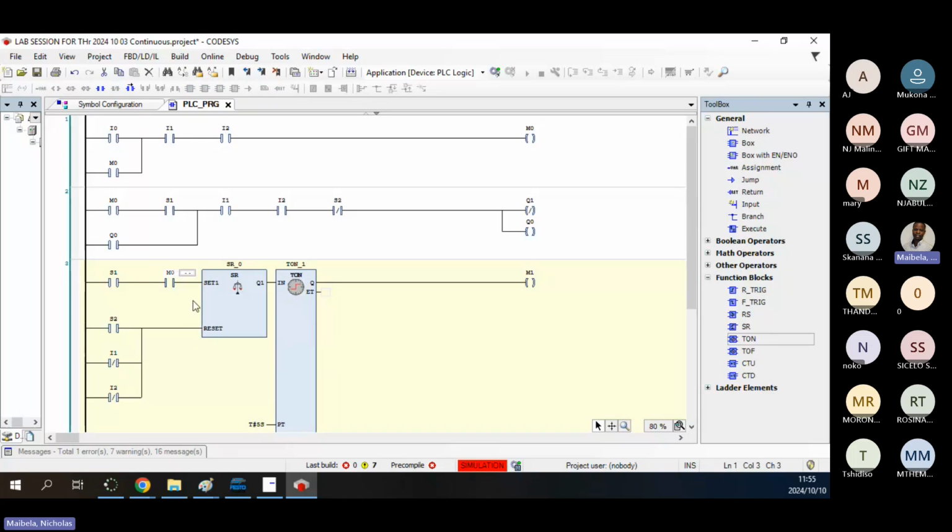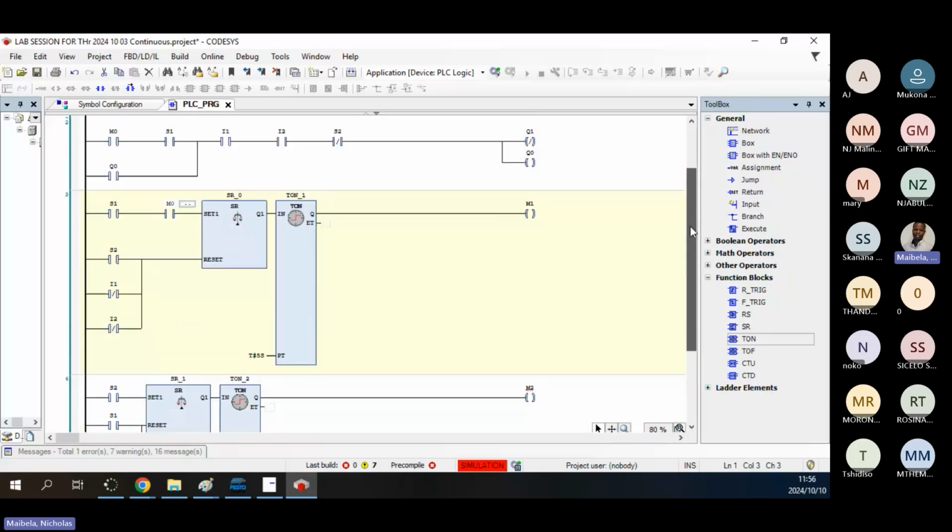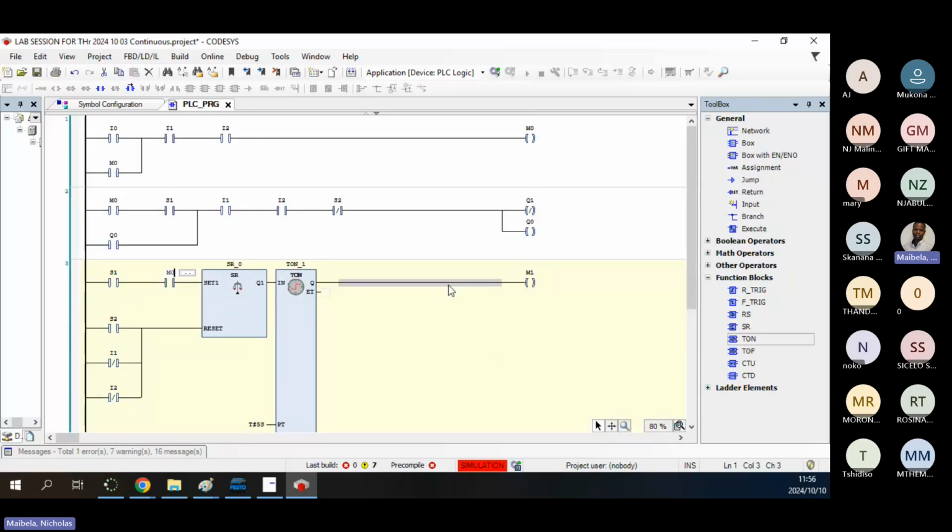It's because this will enable your circuit to move continuously, right? So when you are doing this delay of advancement and retraction, you're always putting your stop-start output to where your timer starts running from the rear end position timer.